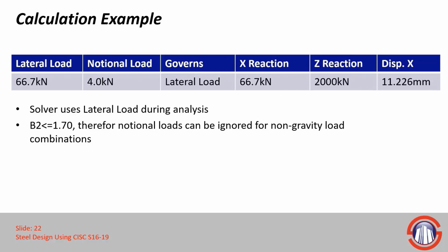And this is also a 2D example, and that was done for simplicity's sake. It doesn't have to be that way. This could also be in 3D, and in fact, the 2D example doesn't necessarily do everything justice. In 3D, the solver would actually automatically reorientate the loads in the direction that has the most destabilizing effects in the X and the Y. So whether the positive or the negative direction.